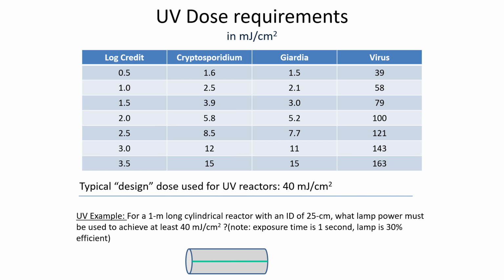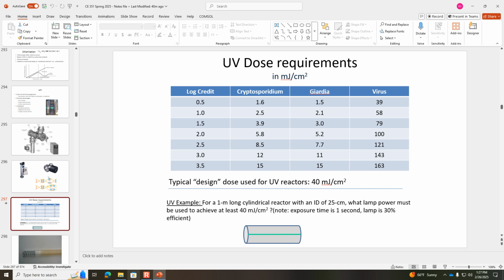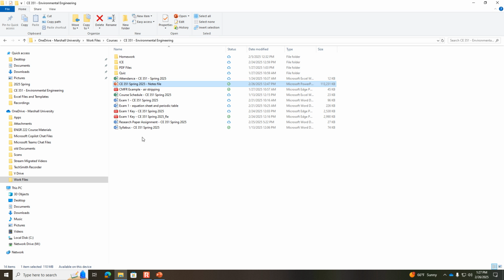Because a watt is a joule per second. So the 30% efficiency then means we have to divide by 0.30. And so the input power required is 1,047.2 watts of input power. And you know, that's about as much electricity we could get out of a normal plug. This is not a huge industrial size reactor.